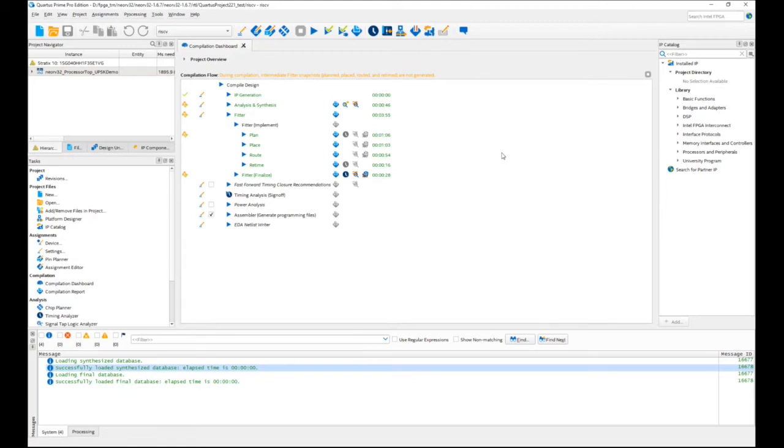Also, the way the clocking is done inside of Stratix 10 and Agilex is a little bit different. There's no concept of regional clocks anymore inside of Stratix 10 and Agilex. It's called a synthesizable clock tree network. What that means is that the clock is only turned on where it's needed. In places where it's not needed, it's turned off. Whereas in previous families, Arria 10 and older, there's the idea of global clocks and regional clocks, and those clocks would light up the entire region, regardless of whether there were resources inside there or not.